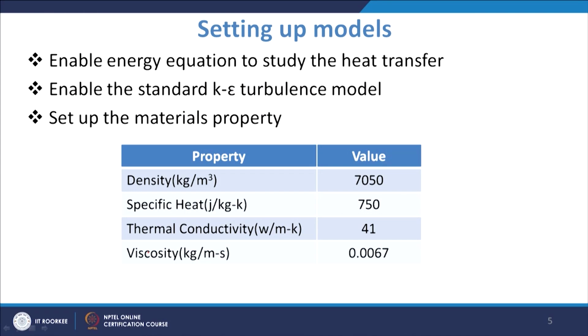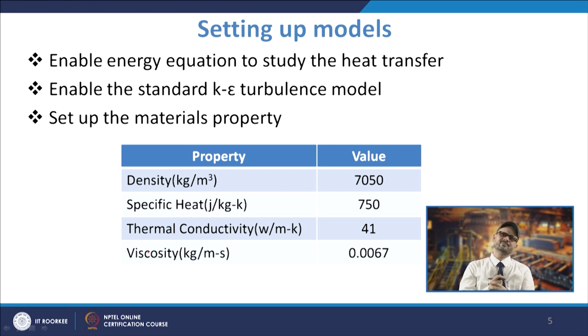Now, you are going to set up the model, and before that you may identify the different zones also inside. So, you can have the identification of inlet, outlets, then you have the different walls you can set as the walls, and also you can have the zone as the continuum, where the liquid is there, so that you can set it.